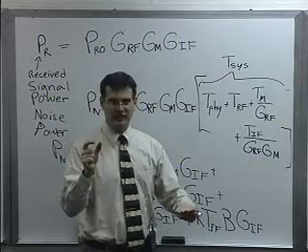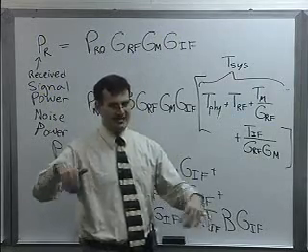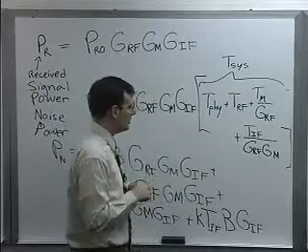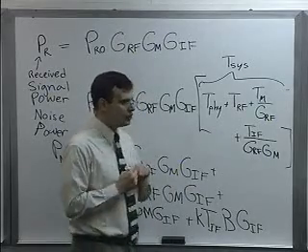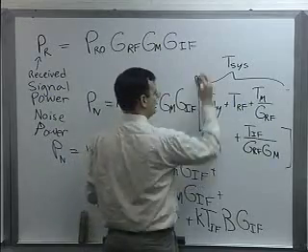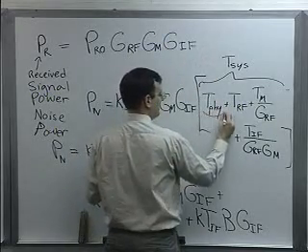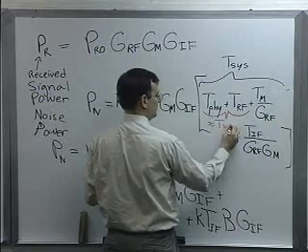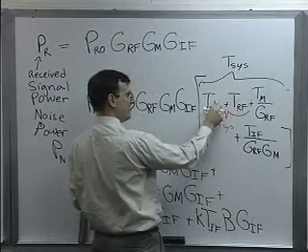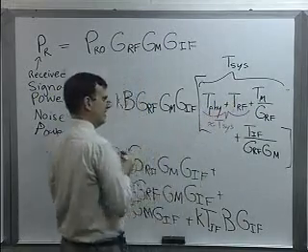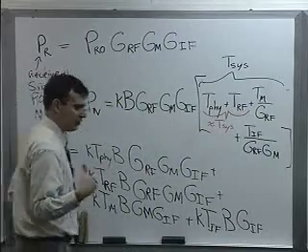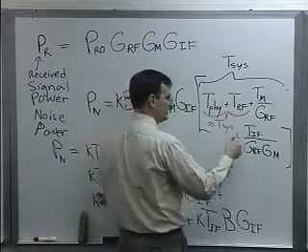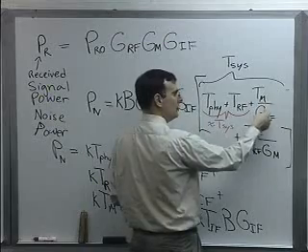What the designers of that device are really after is a device that will add as little noise as possible to your very sensitive and weak, easy to corrupt RF signal. So in this class, unless you're told otherwise, if you have a good LNA, your system temperature is approximately equal to those first two system temperature components, your physical noise from the antenna and the LNA device temperature. Why? Because if it's a good LNA and you're getting at least 10 dB of gain, 20 dB of gain, something in between there, then this is going to be a large unitless number, G sub RF,